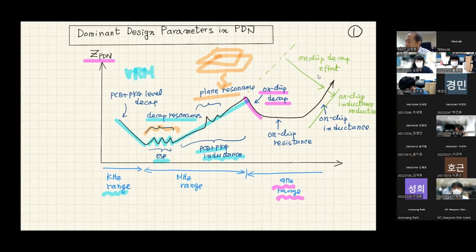So we can bring down the impedance by putting the capacitors. But this on-chip capacitor is a very expensive solution. But the only way we can bring the impedance down to low impedance is on-chip decoupling capacitor. That is the subject of class today.